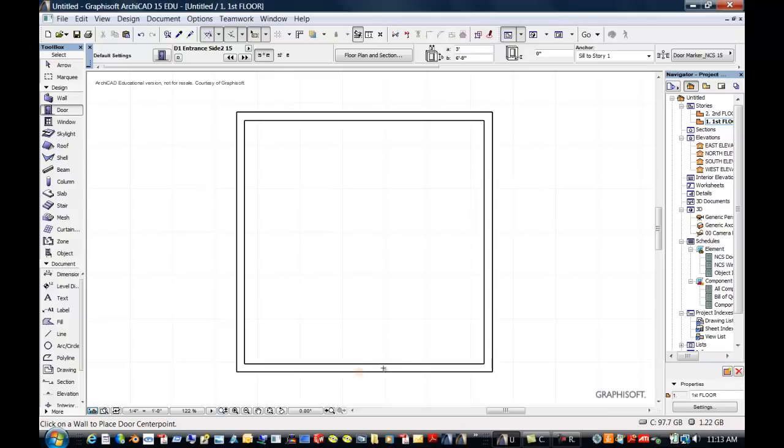I'm going to go, this is up to my wall. This is called a Mercedes cursor. By default, this snaps to a midpoint. So I have a midpoint. When I'm on that midpoint, I get my check. And then the next little question this is actually bringing up is, where is my door? Is the door here? It's there. I can select here and it will put a door there. And so by just selecting in a certain area, the door will appear.